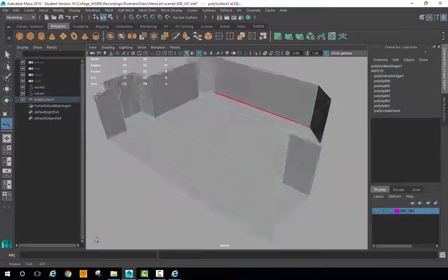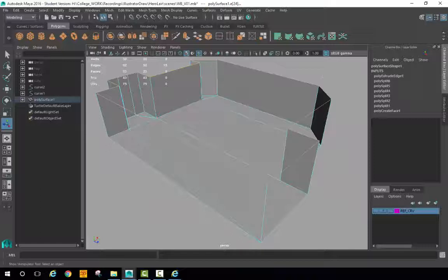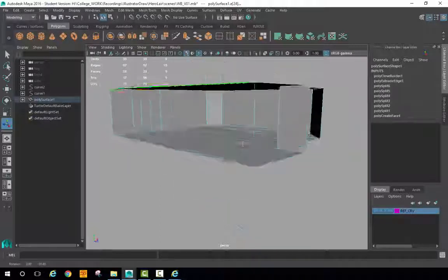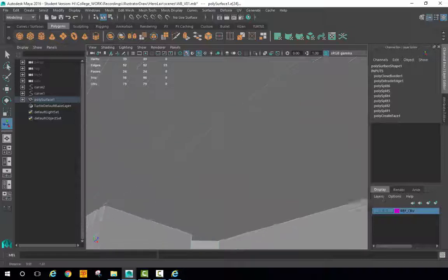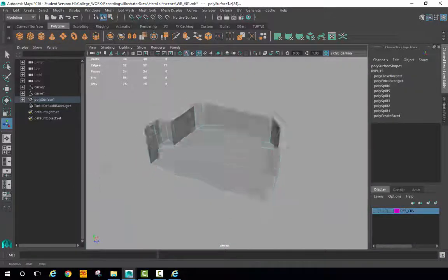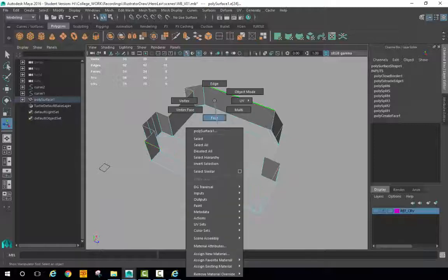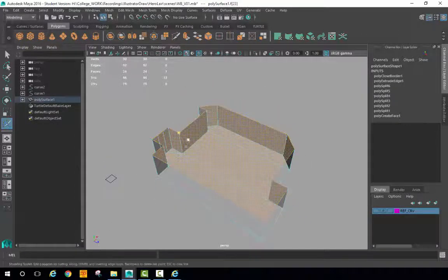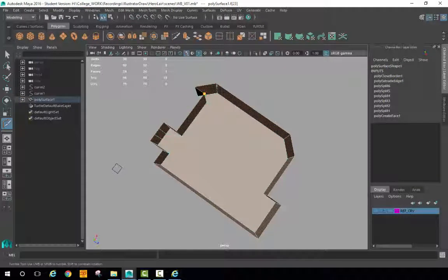And then holding down shift, what we have is the fill hole option. We can get to that in a couple of other ways as well. I'm just going to press fill hole, and you should see that the edge has been filled, and this is where I can now go in, select that face, select it from behind if I want, and use the multi-cut tool again, and we can begin to cut that whole shape up if I want.